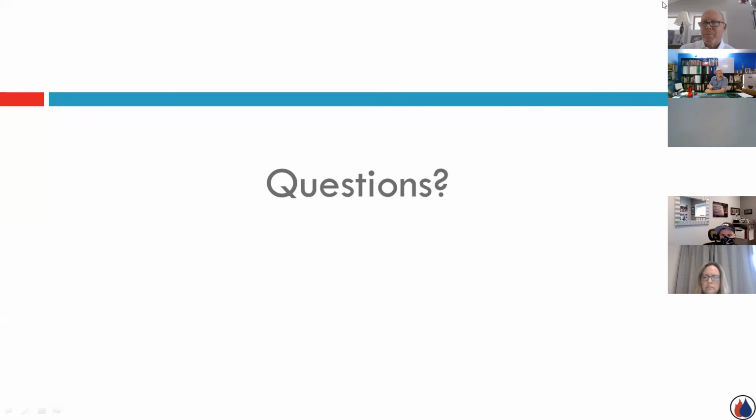The one question came up, I think we answered it, but I think it was questioning multiple boilers in primary, secondary with multiple Ts. And I think you're right about that last example. Meaning what? To do it, not do it, what happens? Yeah, I think it was to do it in the sizing, and I think we've answered with always do them as one set of Ts with common boiler manifolds. Is that like the second picture, the final example? Yes.